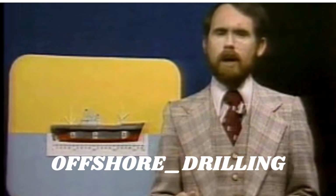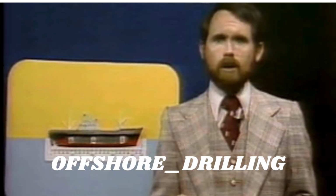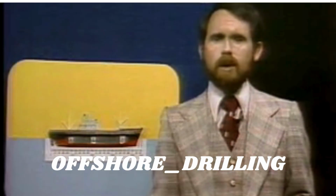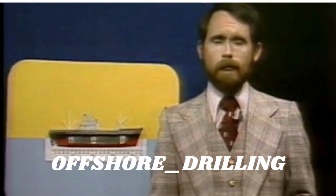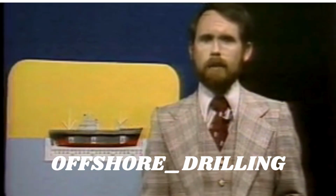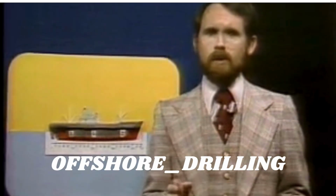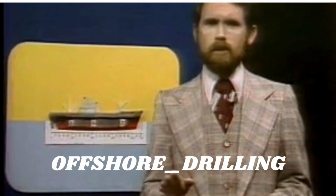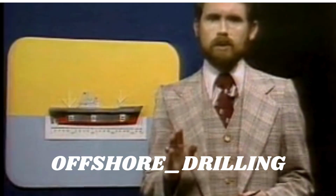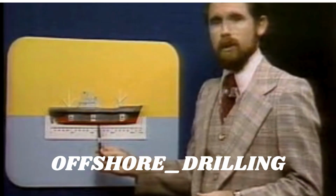In order to find the actual LCG of our vessel after loading, we must take into consideration the LCG of the vessel prior to the loading operation. Let's assume that the vessel we have been talking about had a displacement prior to loading of 7,000 tons, and its LCG, as determined from the hydrostatic curves, was 205 feet aft of the forward perpendicular.